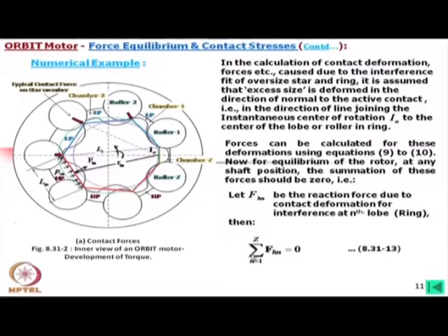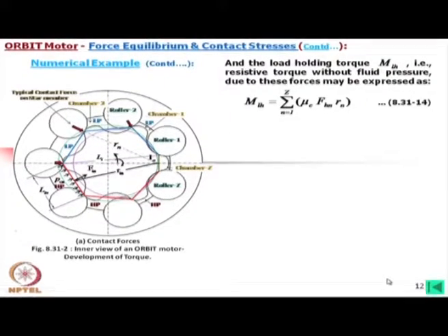Then the summation of all such forces due to the interference at no pressure must be equal to 0. We must satisfy that condition to find this force, and then the load holding torque must be equal to that force into the coefficient of friction into R n.